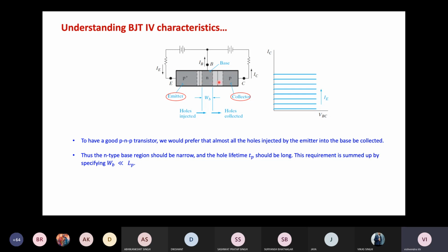But because of the reverse bias on the collector-base junction, the depletion region can grow so much that both of them actually punch through. That is the case in some transistors, and it has applications whenever the base current is not so important. But that is not always desirable to have.